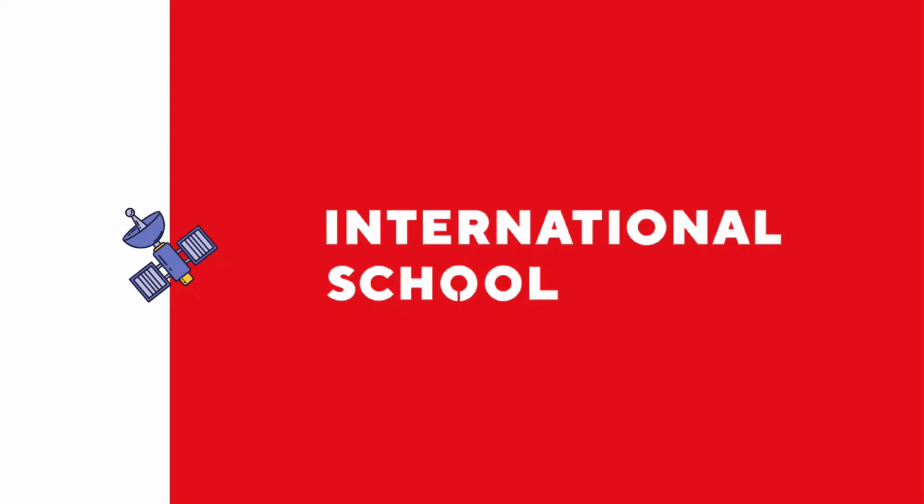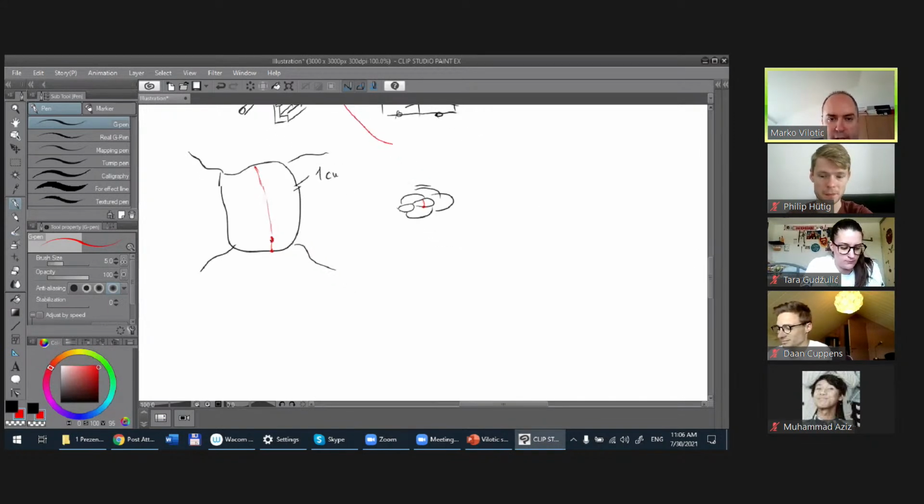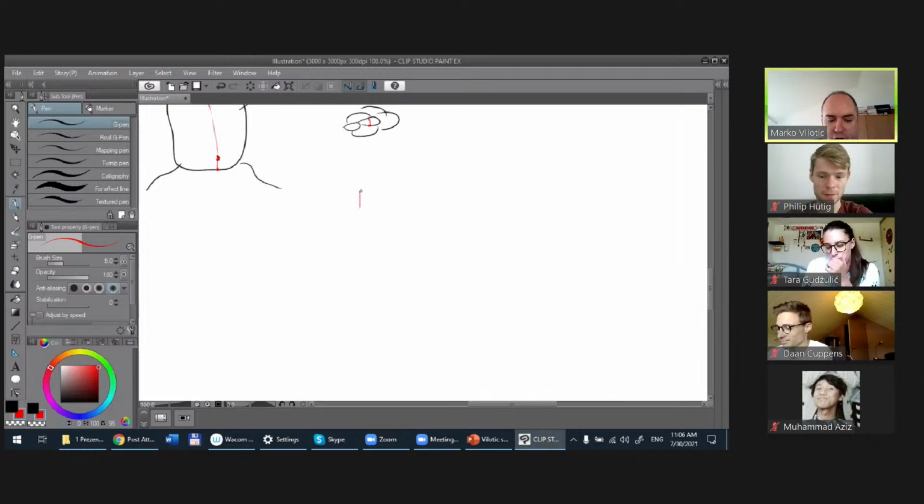Okay, I'm back. For the students who asked me this question: if effective plastic strain equals true strain, it is true, but there are some limitations. First, it's only when you have tensile testing. Of this one, it is true, but only before the necking appears. Once the necking starts, then you don't have homogeneous deformation, and it's not true.